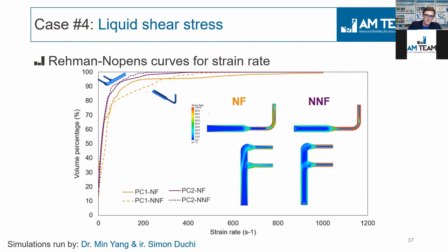We talk about shear exposure. For example, if you have a very low shear, but your liquid stays very long there, you will have a certain exposure that can be equally high as having a very high shear, but very short residence time around that area. Both the overall shear, but also the local shear are very important criteria to look at. And these hotspots probably should be minimized.